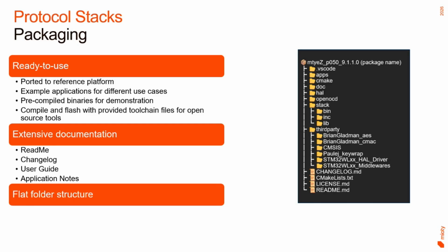The integration with other processes is possible, but compared to protocols like LoRaWAN, mioty uses multiple short bursts with strict timing requirements, and therefore it's recommended to avoid interrupting mioty procedures with time-consuming tasks. Also, make sure to use a high-precision crystal oscillator to ensure accurate timing.